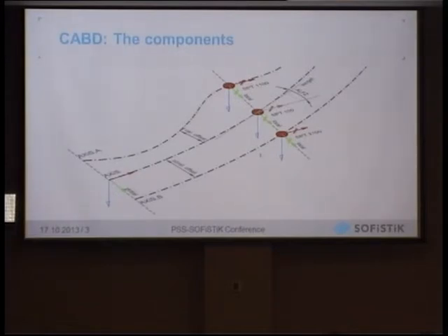So this is the most important thing. The first thing you might model for your bridge, no matter whether it's a beam model or a shell model, will be these axes with the different notions. Maybe one thing I should introduce, that we call this section here, this intersection, which I call support axis, we call placement. So we just say there are placements, points of interest along the bridge axis.